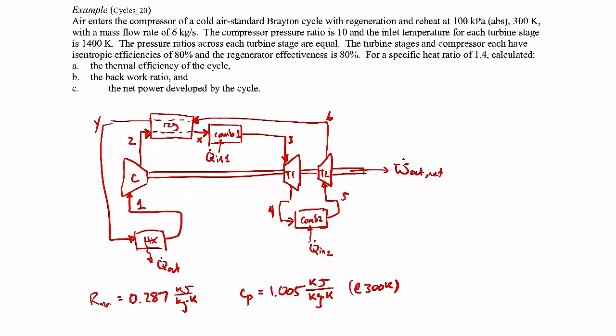So it's a pretty large temperature range. Over that wide of a range of temperatures, the specific heat at constant pressure for air would change quite a bit. So this is not a particularly accurate analysis, but we're asked to do it in the problem statement, so we'll do it nevertheless.